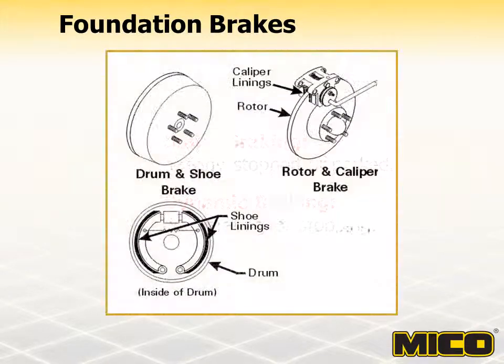Normally, an automobile will use either rotor or caliper brakes at each of the four wheels, or rotor and caliper brakes at the front wheels and drum and shoe brakes at the rear wheels. In automobile brake applications, the front brakes do the majority of the work. On the most basic level, all hydraulic brake systems share the same principle: muscle strength amplified by leverage. Your foot presses on the brake pedal, which displaces fluid from the master cylinder and causes pressure to increase throughout the brake circuit.